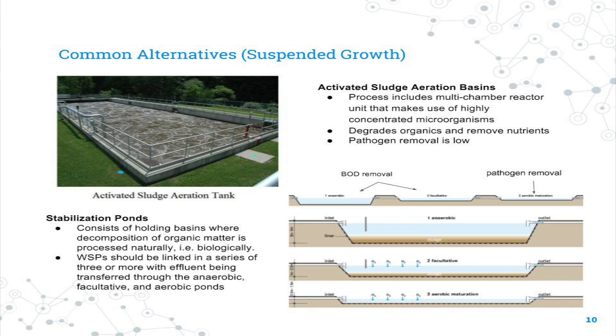Once the wastewater has received sufficient treatment, excess mixed liquor is discharged into settling tanks, and from there, the active sludge is recirculated to the aerated tank for further treatment before discharge.